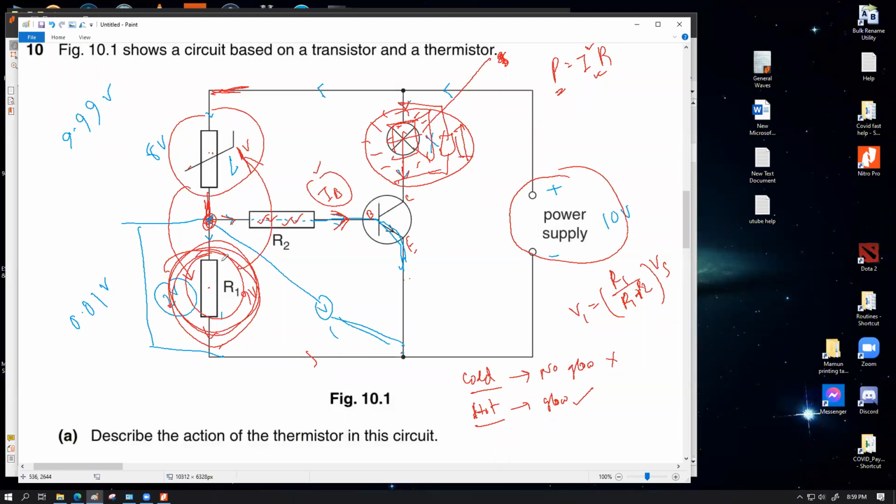So different resistance values over here will essentially control the different voltage remaining for this lower part of the circuit, which can control exactly at what value the current IB goes high enough so that the light actually starts to glow. So you can essentially control the temperature sensitivity of this thermistor, or of this entire sensing circuit, by controlling the resistance of this.